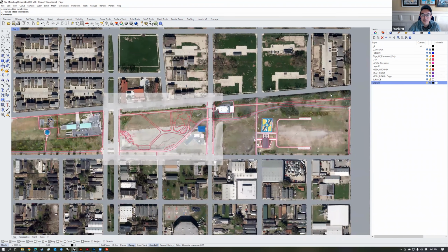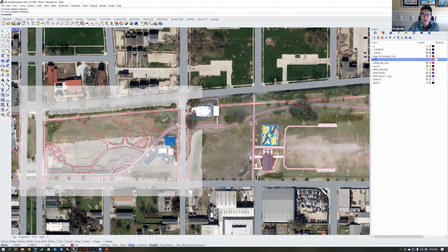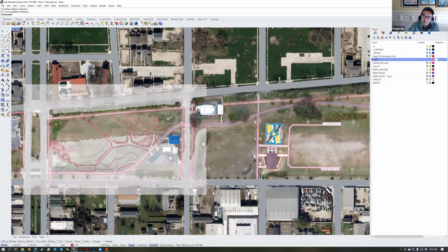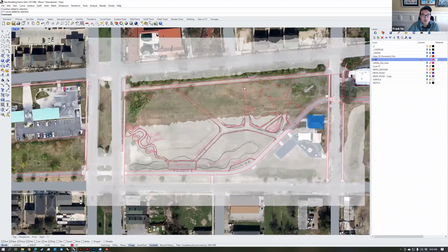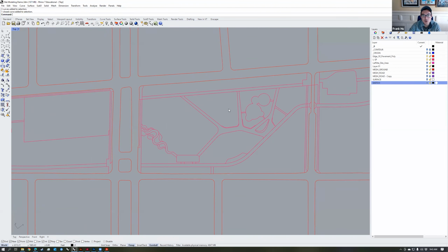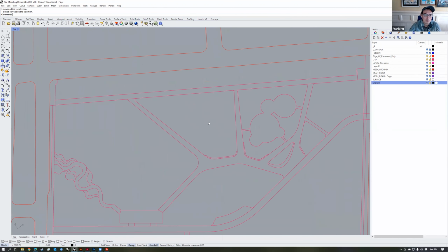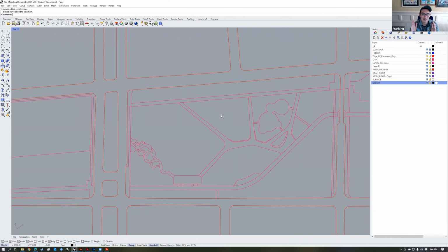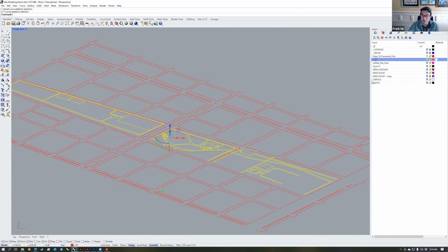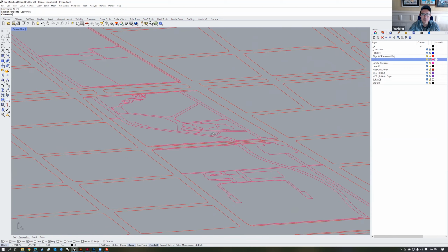You just need to look at the existing conditions, draw the line work for portions of the existing conditions that you're not going to change, and then draw your plan. Whenever you draw your line work, try your best to draw it neatly. What I mean is avoid sketching everything freeform, but rather draw center lines or edges, using offset tools or fillets to create clean widths, nice clean radiuses, simple drawing techniques, lines and arcs. This is all on one layer and it's all on one plane.